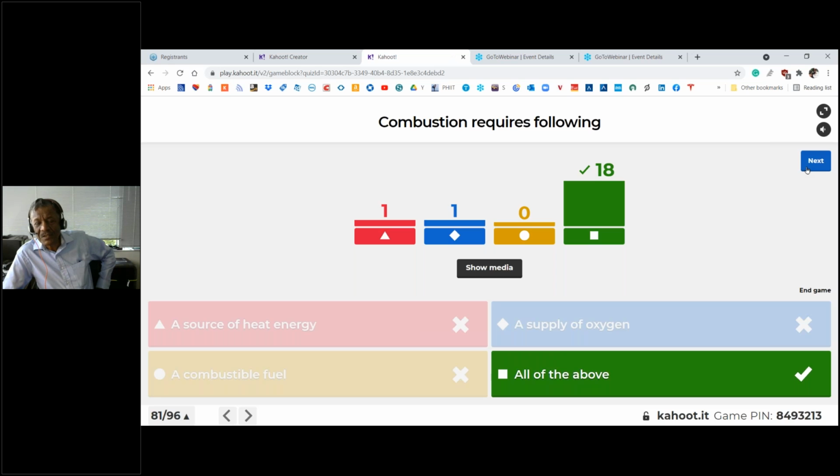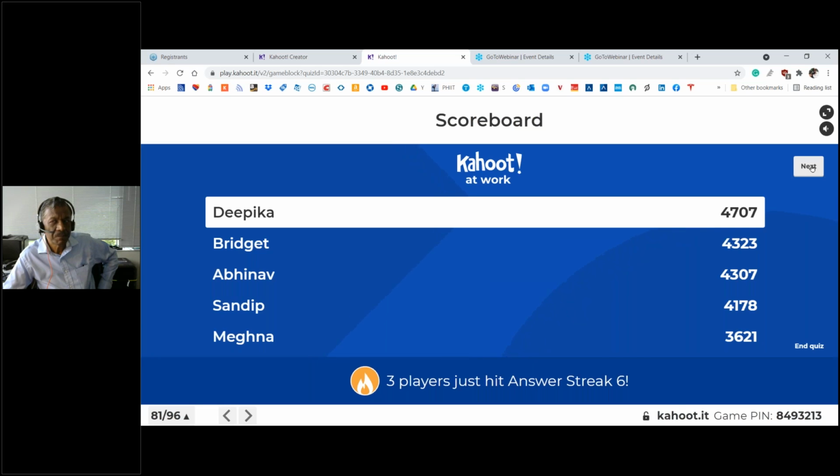There is a parameter called minimum ignition temperature, and unless the fuel is above that temperature, it will never combust. That's why we have an ignition torch or pilot burners or some source which brings the temperature up, and then the combustion starts. And once the combustion starts, it becomes a self-sustaining reaction.